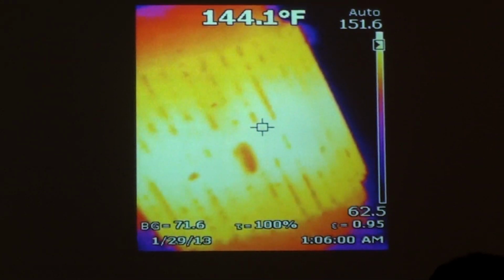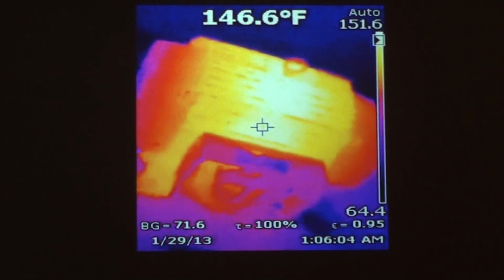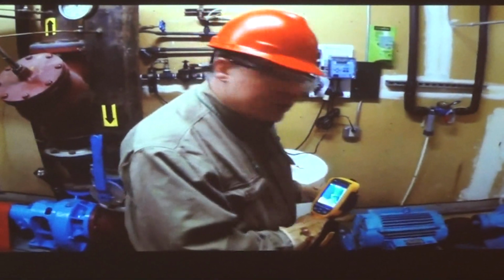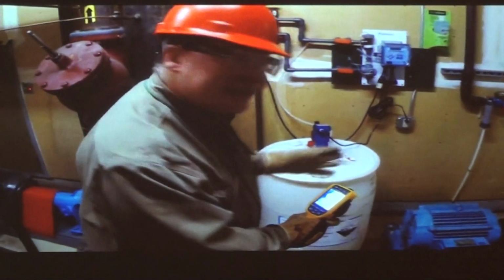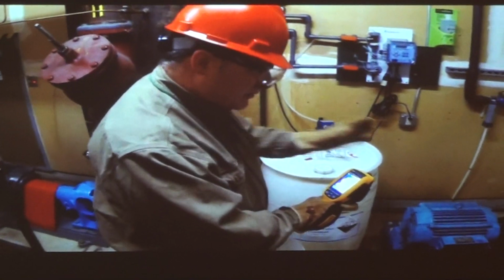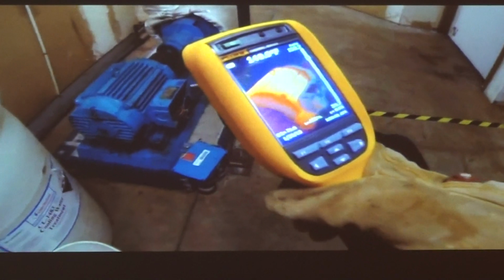Looks quite even. I don't see any issues there. You know, obviously, if this motor were running hotter than usual, that could be an indication that perhaps the cooling fan's not working properly, it's not aspirating properly. I think everything's working okay here. Number one, the temperature is good. Number two, the fan is operating.